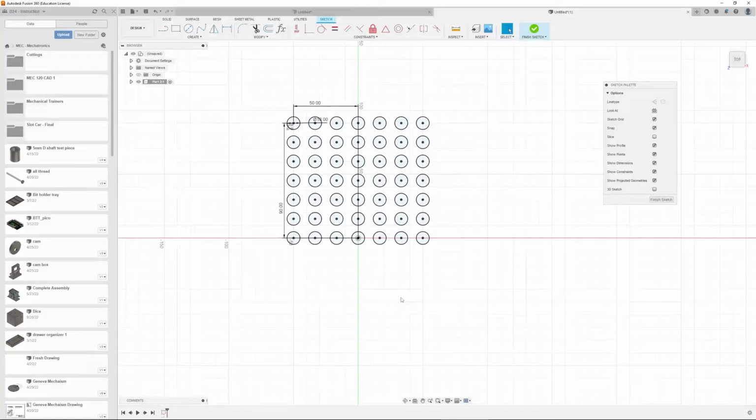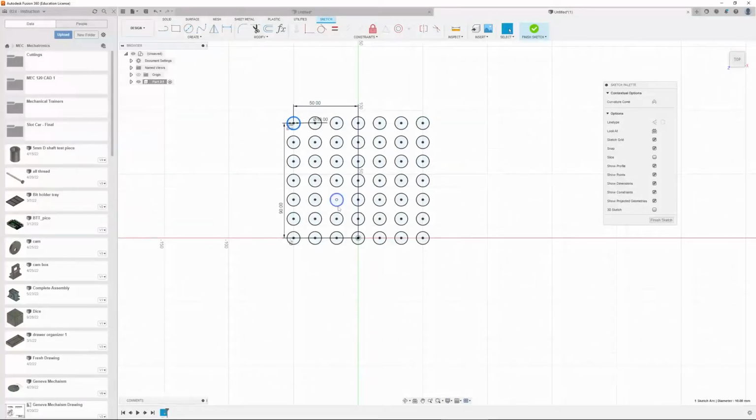Whereas with the rectangular pattern tool, we can simply define a shape, fully define it, and now we can just copy that pattern over and over again as needed. So for certain types of objects that you're going to CAD in this quarter, these tools, the pattern tools, will save you a lot of time. So keep them in mind.